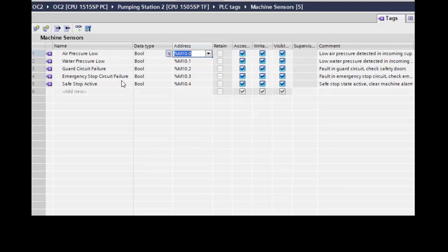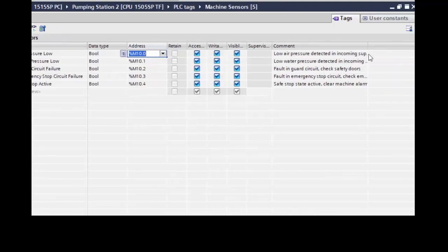Now, in a normal operation, we may start to engineer the alarms inside of the operator panel. With the Siemens equipment, it's quite common with the older kit to use things like marker words and to manually type the alarm text in. What we'd like to show with doing things like ProDiag is giving our tags symbolic names that are intelligent and mean something to us and to an end user, but also utilizing systems where we can write comments.